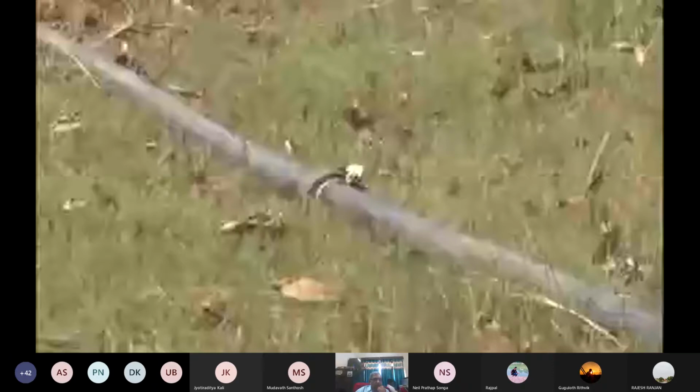So this is one coupler in which one lateral pipeline will be attached with another lateral pipeline, and on this coupler you can see a riser which is of 1 inch diameter, 1 meter long, and this end is connected with a pressure gauge.